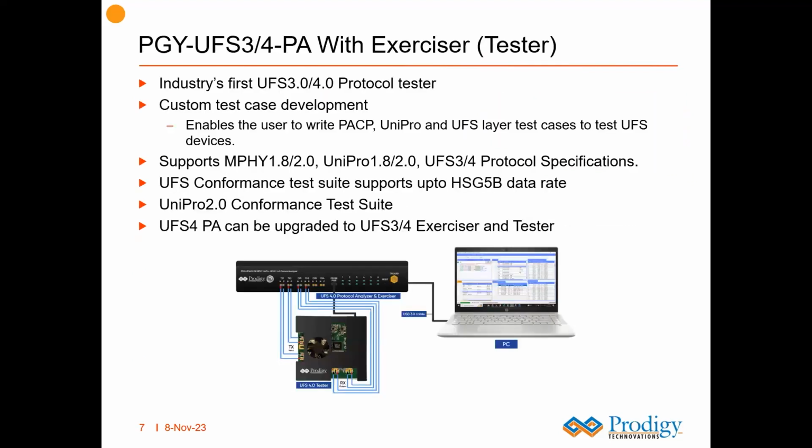The UFS tester, which is one of the key focuses today, is the industry's first UFS 3.0 and 4.0 protocol tester, thoroughly tested on multiple devices and working pretty well at HS Gear 5B data rate. Users can write their own custom test cases using our script.